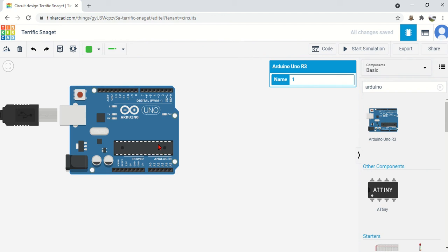And here I want to connect an LED on the pin number 12 so that it will be an output, and I have to connect a push button to the pin number 2. So, the push button is acting as a switch input and then LED is an output. So, I have to control that LED using that push button. When I press the push button, I have to glow the LED which is connected at the pin number 12.